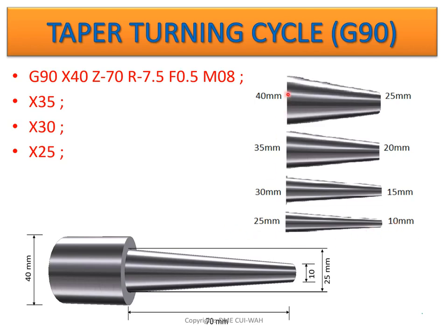You can see in all these parts the length is same. There is no change in length. Only the diameter is changing. On the one side it has reduced from 40 mm to 25 mm, and on the other hand it has reduced from 25 mm to 10 mm. So this was the case I was talking about in the previous slide. In these four passes, you have reduced the diameter from 40 mm to 25 mm on one side and 10 mm on the other side. This is our final job. This picture is our last and final job workpiece.